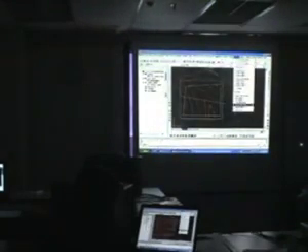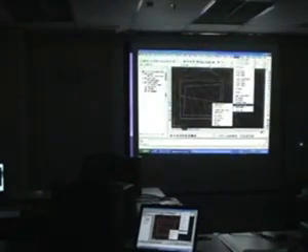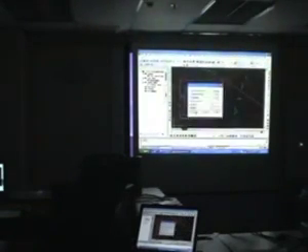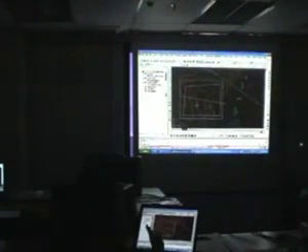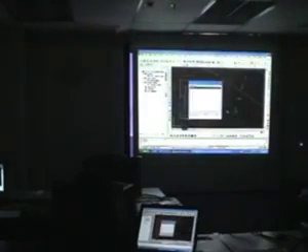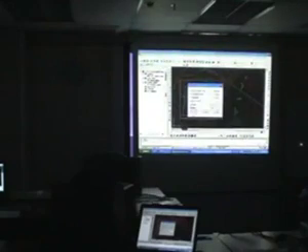The third method, using the section volumes, is a bit different because we can't run the volume calculation straight away. You need to sample some sections first. So this is what I'm going to do. I'm going to sample some sections. Just hit OK. It's sampling sections across my original and the proposed level. And now we run our calculations. Just click calculate volume total and select the site. As you can see, within the section volume method, there are two further methods.